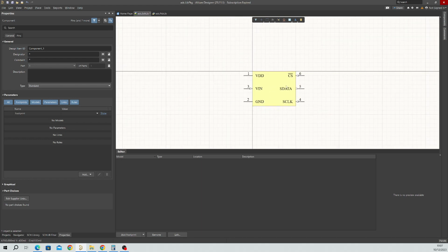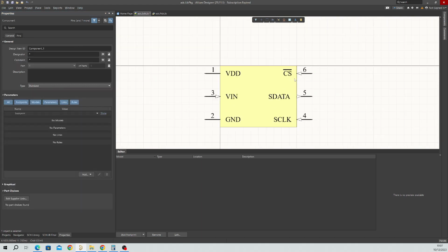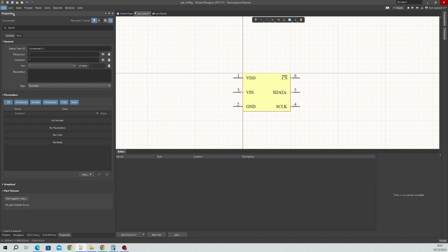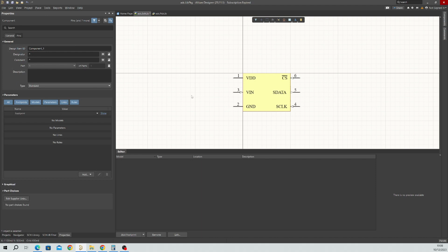Okay, there are other ways. You can do an active low input and all that sort of stuff. They're not so common. I tend not to use it. I tend to just use the text view version of it. You could have also called this CS_B. That would have also been valid, but this at least looks like the symbol that we want to generate, and it's from the data sheet. So that's everything there. So now we want to go and find this part.